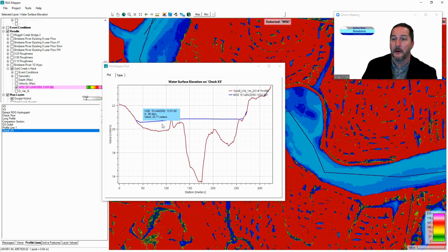The method that I've shown you right now is more helpful if you're interested in a flow rate that stays relatively constant over time. It's almost like a steady flow. If it is flashy and there's lots of storage areas that might be influenced by overflows that are really sensitive to the roughness as that flow arrives, you might still be missing the mark. If this didn't flow over here because this was smooth or this was rough or whatever it was, that's where models that can do this at every time step might be better suited for that sort of an application.